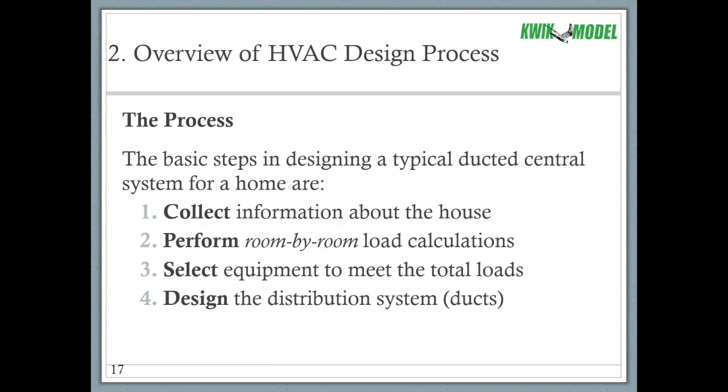The next step, once you do your load calculations, and remember the load calculations is what the house needs, is to determine a piece of equipment that's going to meet those demands, those loads. And so that's step 3, select equipment to meet the total loads. Then once you have that equipment, you'll be able to determine the total airflow that equipment provides at ideal conditions, and then you use that number to design the distribution system, the ducts.